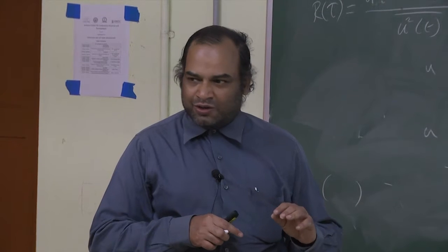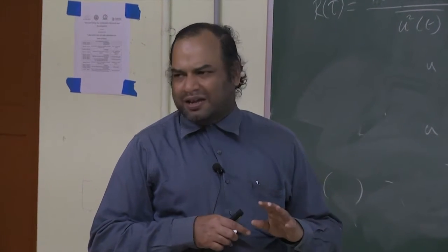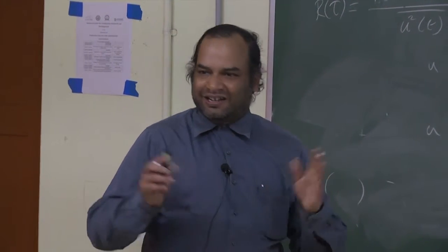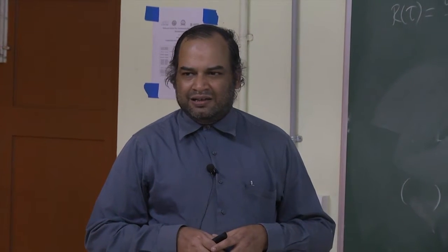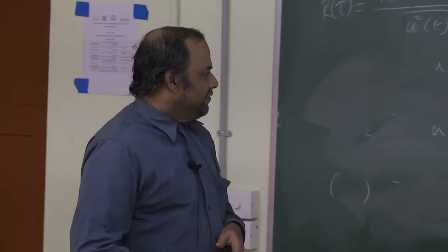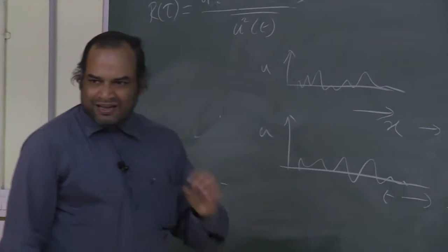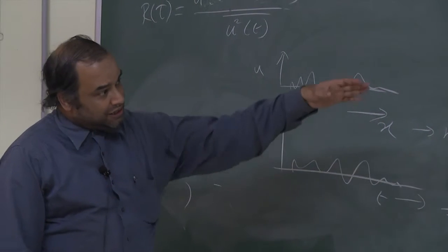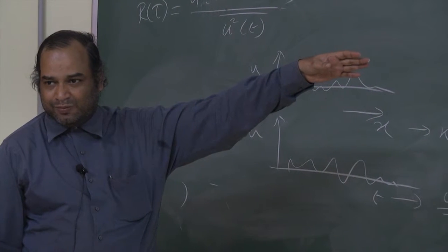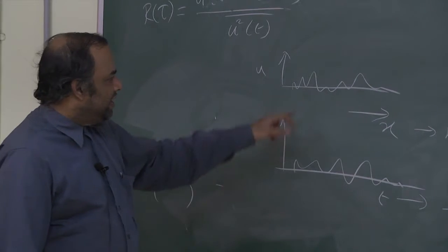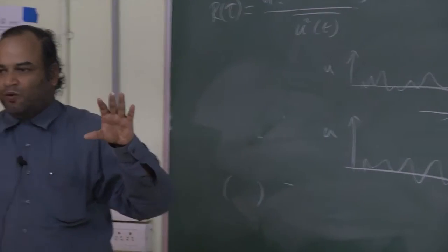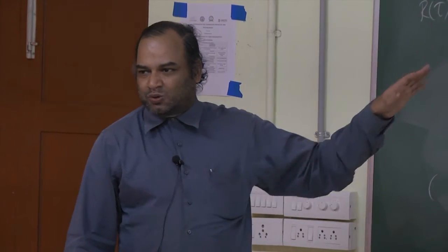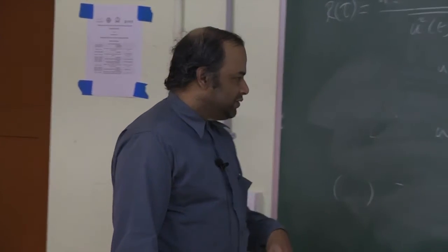There are also what are known as the high speed PIVs. They are not yet very large in terms of temporal resolution as yet. You can go up to 1000 hertz or so. Anyway, I can get an instantaneous shot from a PIV and construct this kind of picture immediately in principle. But you are only limited by your interrogation volume in space and so on. That's the usual thing with power of the PIV laser and so on.